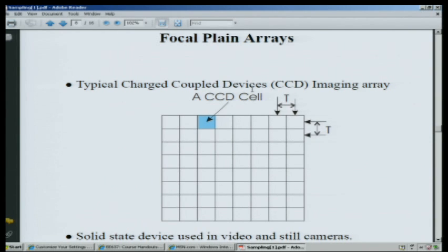And each CCD cell counts photons, and then what happens is that they have what they call a bucket brigade sort of technology, where they have switch capacitors, and the switch capacitors basically can shift charge around through various tricky maneuvers, okay? You know what a bucket brigade is, right?